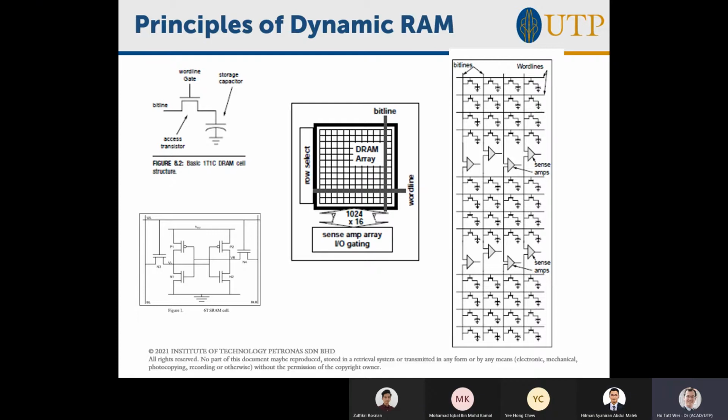Okay, now you start to see a problem. You're putting a small charge on the capacitor. It's not even 1.8 volts here. This is several tens of millivolts to hundreds of millivolts. That's the amount of charge across here. What happens if you leave this capacitor for a long time? What do you think happens? Will it retain its voltage?